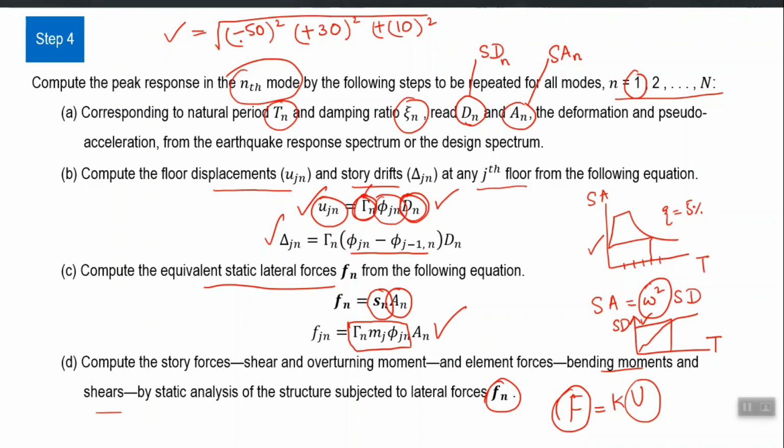So, whenever you have peaks from different cases and you want to combine them, there are different statistical methods which give you some resultant peak, and one of those methods is SRSS, where you do not add the peaks directly; you square them, sum them and take the square root. So, you normalize them, and kind of get a resultant combined response.